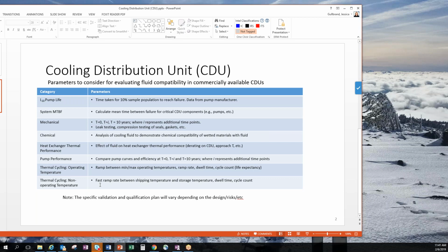But once it goes out of that comfortable zone where everyone's 100% familiar with what you're doing, they can't tell you, because it depends on, like I said, temperature. Basically, if you've got a centrifugal pump, you've got two bearings and a seal. That's the only thing that's going to break. You can probably figure out how long the bearings are going to last based on temperature and load and so on, but it's really hard to figure out how long the seal is going to last. I've gone down this road before, where people asked how long it's going to last, and I called the pump manufacturer and he said, "Oh, it's going to last forever." I'm like, well, thanks.